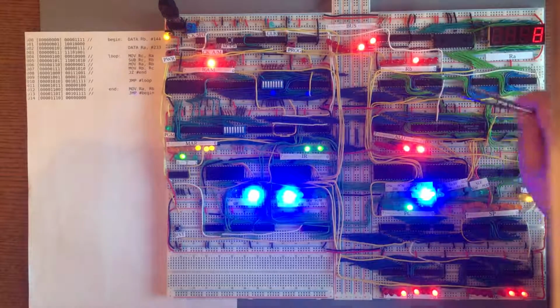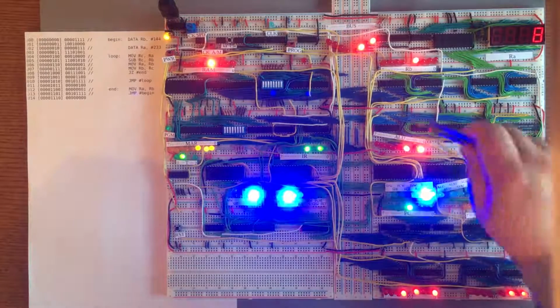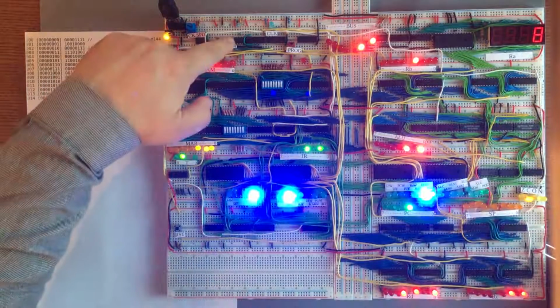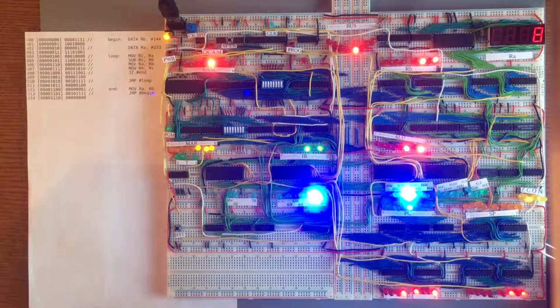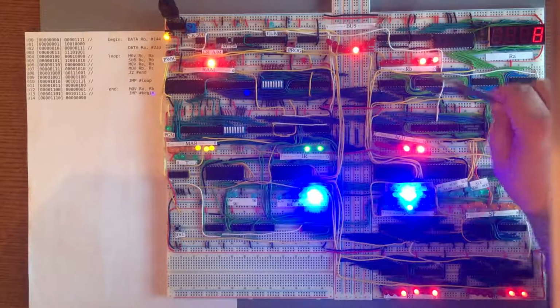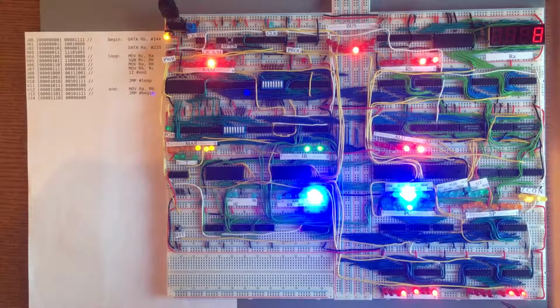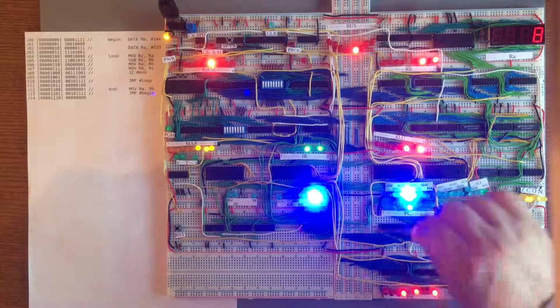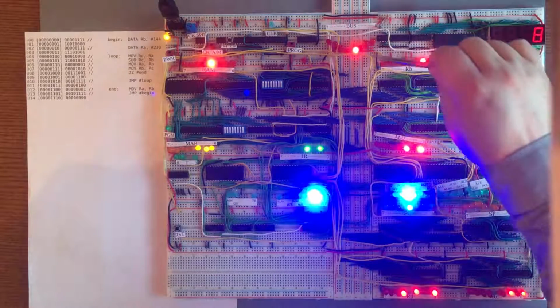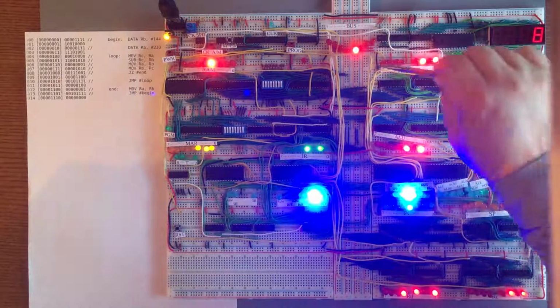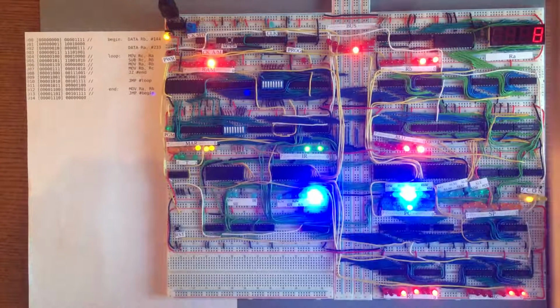And so the B register on the next clock tick is going to take that value and store it inside himself. So if I just advance the clock by 1, there you see, it happened. So now that value which was in the C register has been transferred onto the bus. And then on the rising edge of the clock, the B register has taken that value and stored it inside itself. And that's all that registers do, really. They output their values onto the bus and they read values in from the bus. And so we're going to have a look at how that works.